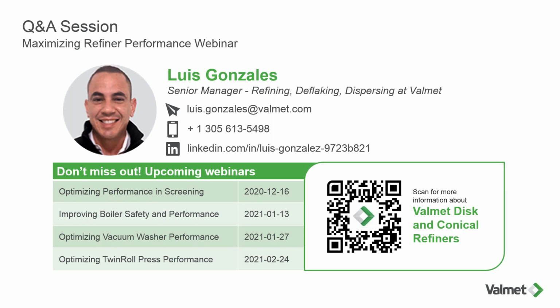Another good question. I have another question here about when applying freeness control, how and where do we measure freeness? I'll take that as a two-part question. There's a second portion of it. The answer is that the system capabilities are such that one unit can handle 20 sample points, and the samples take at max 3 minutes. That's considering the full cycle of taking the sample, analyzing the freeness, putting out the number, and then recalibrating itself. So it completely cleans itself out and recalibrates itself.